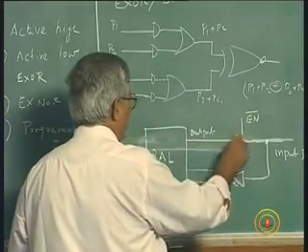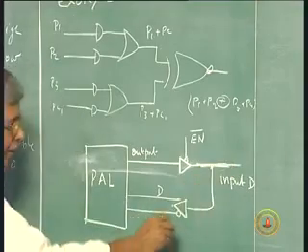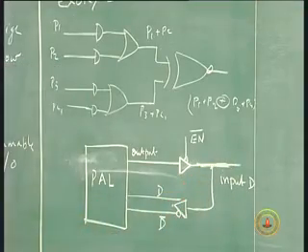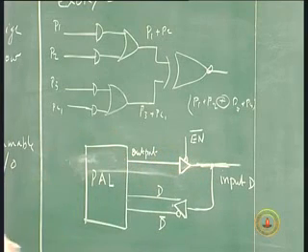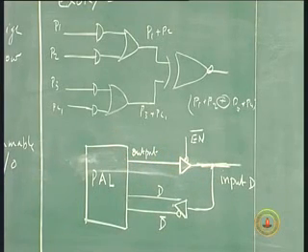If En is 0, this uses an output pin. If En is 1, this uses an input pin, where a new input can be connected, and its complement also is available for implementing your logic using that extra input. This concept is called programmable I/O.